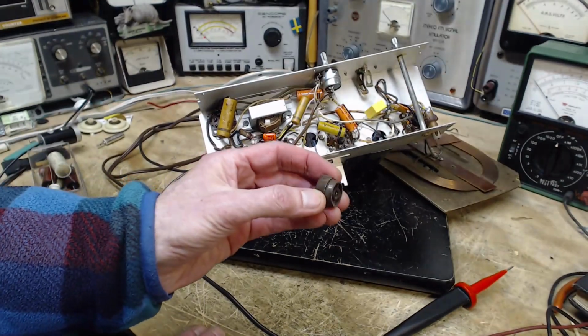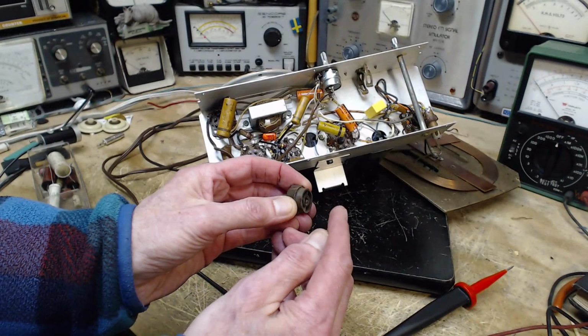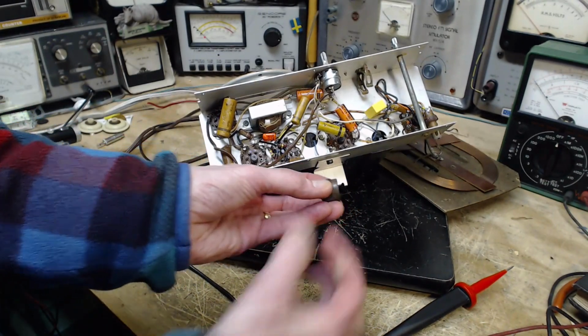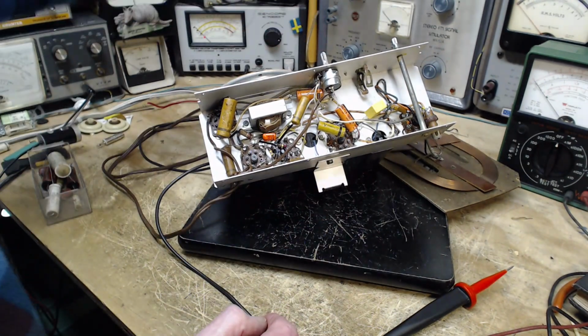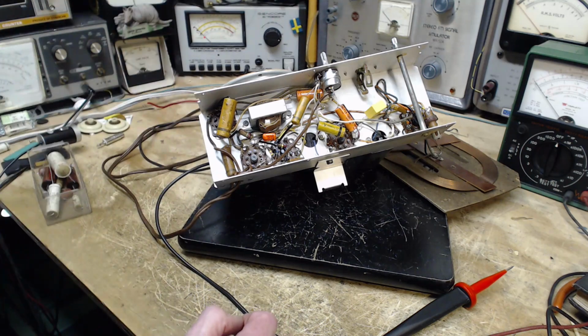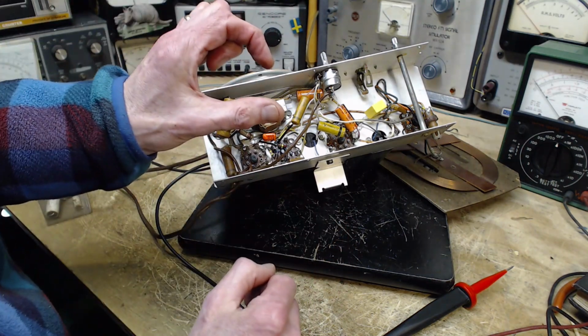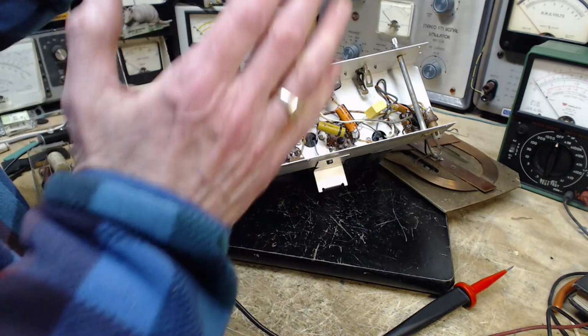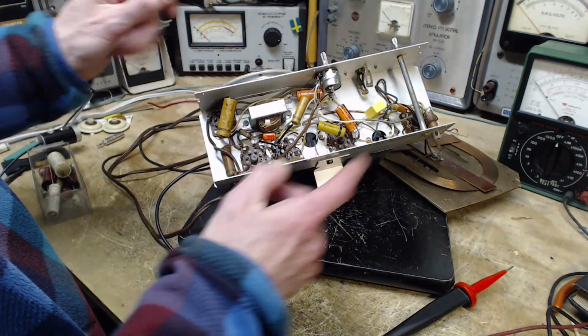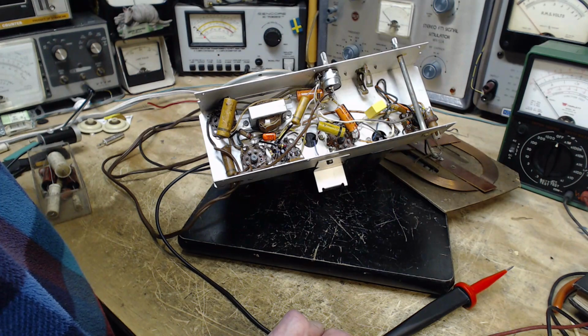Unlike this knob, they extend out, so they can reach into the chassis hole where this is hidden. You reach in. That's one. So if you have a radio like that, you pull the knob off. It has a long collar going in, and this is recessed. That's a hint. Total hot chassis, B minus right on the chassis.